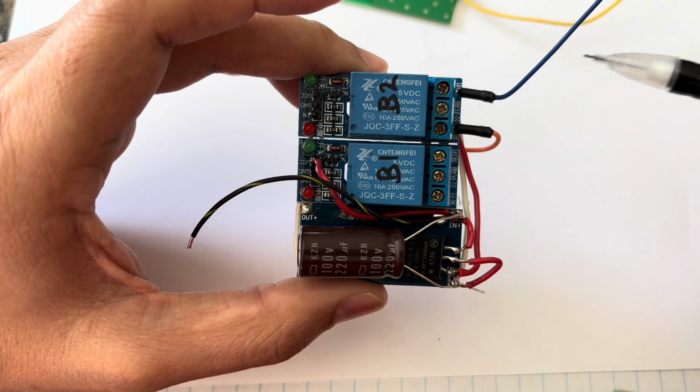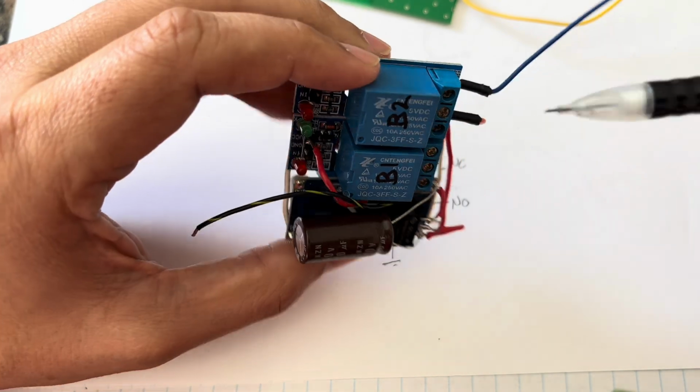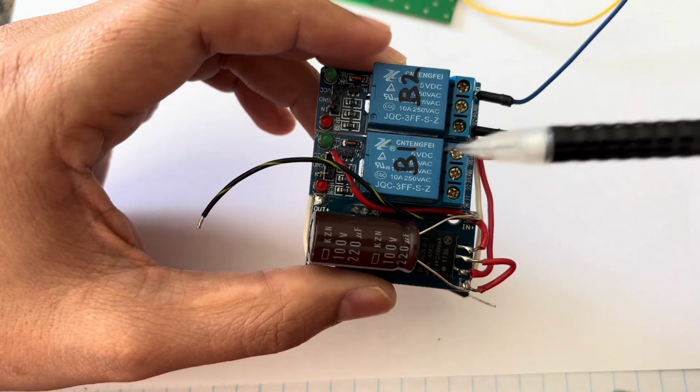Now, the advantage of this one is that you can PWM and it doesn't wear out as fast as the mechanical relay because you have no moving parts really. So let's go over if you decided to use a mechanical relay. They usually come in these really nice packages, like these modules.